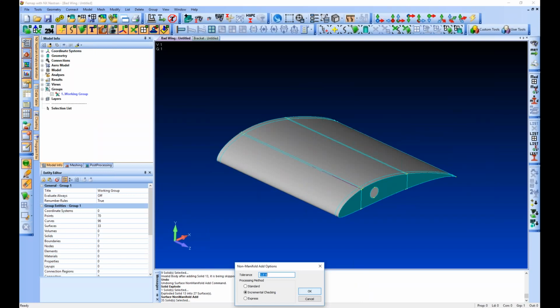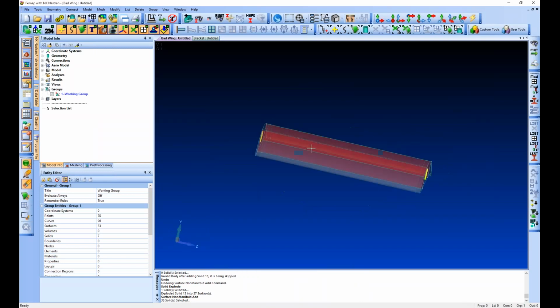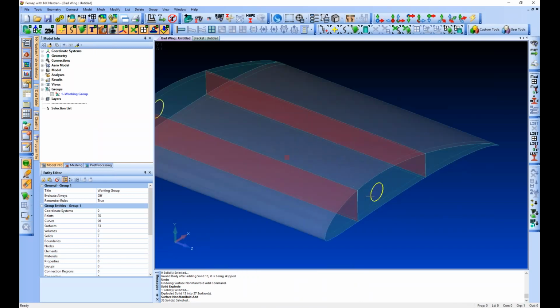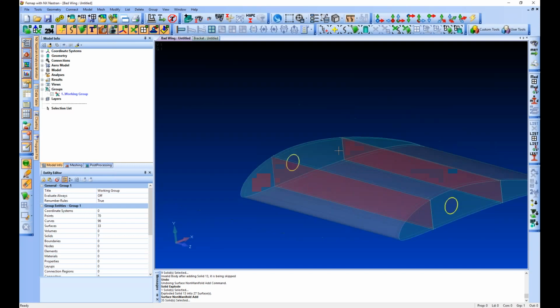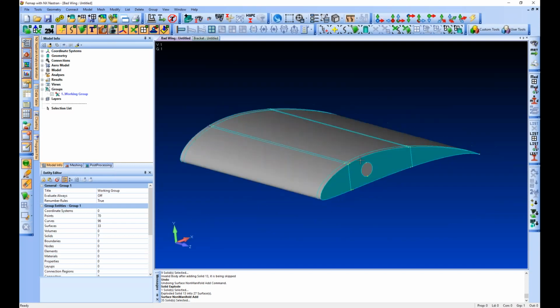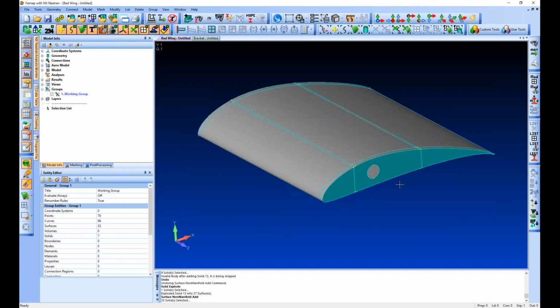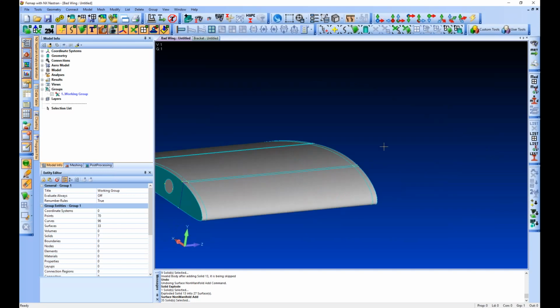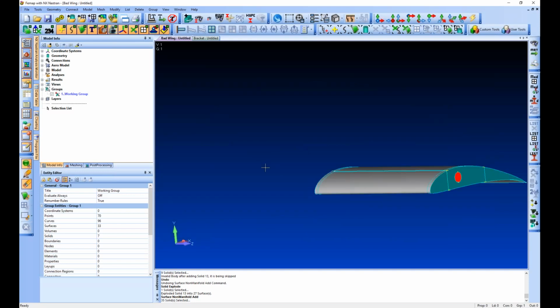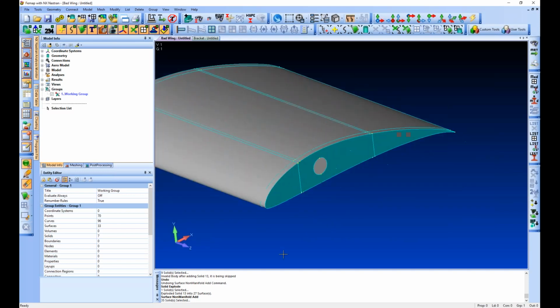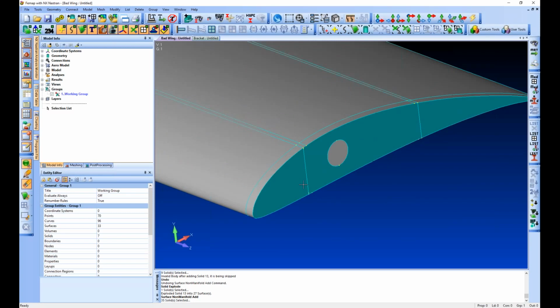If we repeat the same thing, we'll just select all of these separated surfaces and click OK. We'll notice that it did work this time. So we have two free edges, but those are the pass-throughs, which is what we'd expect. So this is non-manifold added, fairly easy to mesh, clean geometry that took 20 minutes. So fairly fast, probably faster than handing it back to the designer, and you know it's tailored to you.